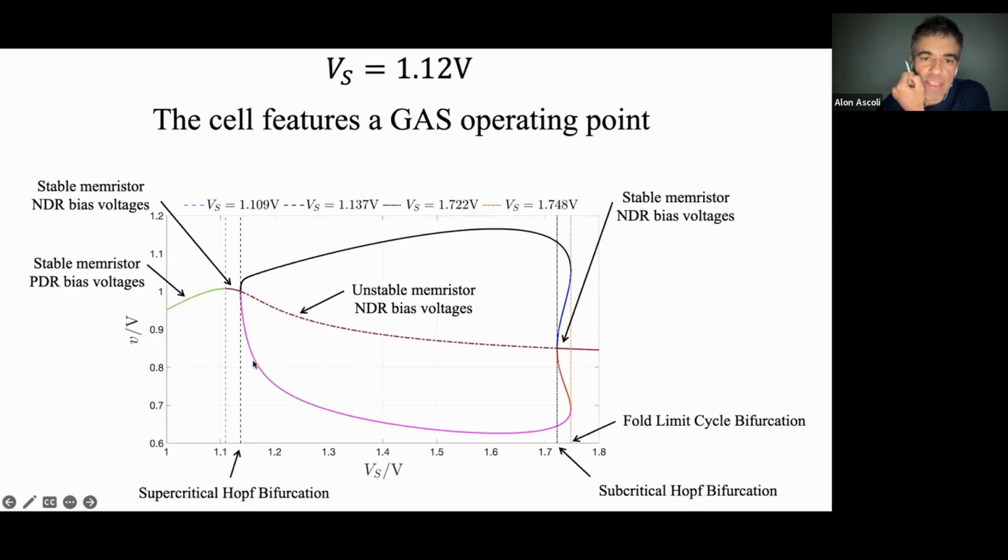The first on the left, of course, the shapes are different because, quantitatively, we cannot expect that our second order simple relaxation oscillator, I mean, everybody's working with this type of oscillator, so it's a standard cell, but nobody has ever identified this bifurcation phenomena inside the cell. It also gives an idea about how important theory is, because through the bifurcation analysis, we were able to tune the parameters in a very conscious and systematic form to achieve this reproduction of complex phenomena. So as you can see on the left side, we have supercritical bifurcation, then a subcritical, and finally a fold cycle.